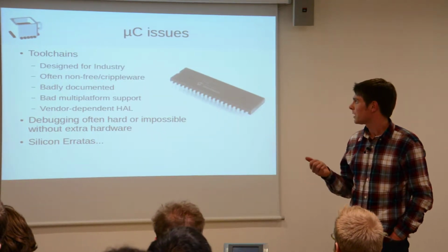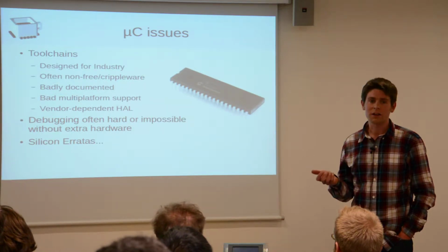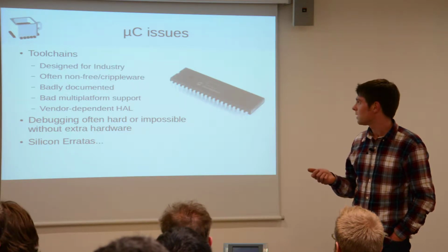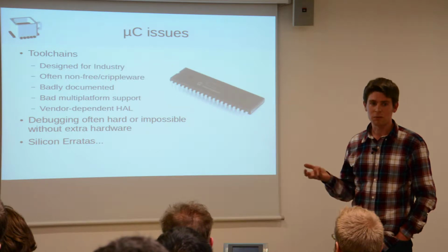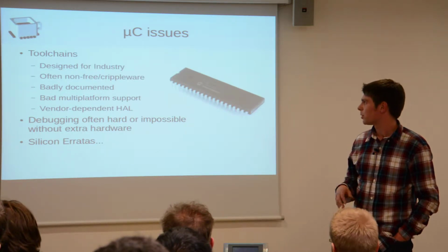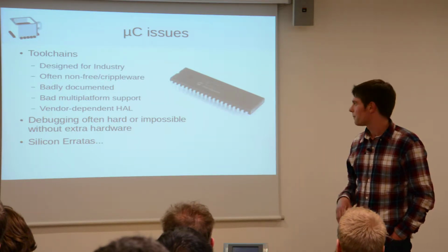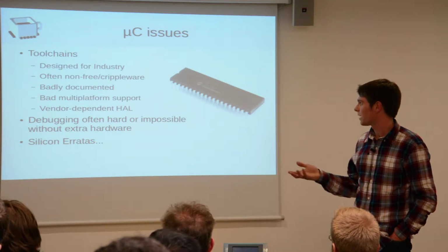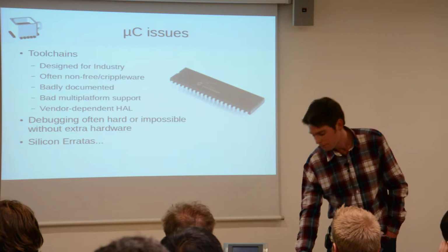But I found one of the real problems, especially on the ARM side, though it's got a little bit better now, is the toolchains. They were originally designed for industry and maybe maintained by companies that have a vested interest in keeping them non-free or crippleware. They're usually quite badly documented, with bad multi-platform support, and usually you need an extra bit of hardware for debugging as well. And even when you've done that, you probably have silicon quirks if you're working at a low level that you have to work around.